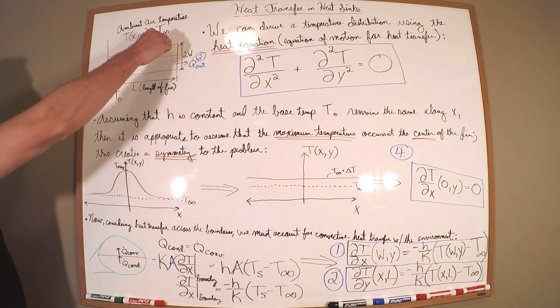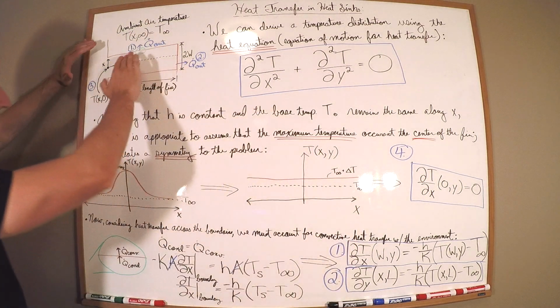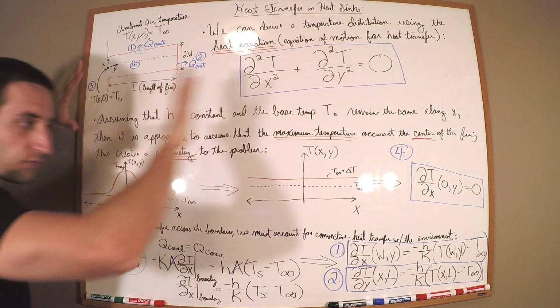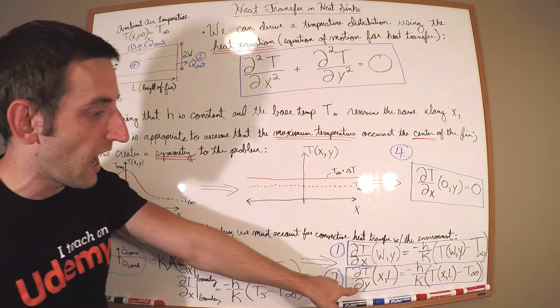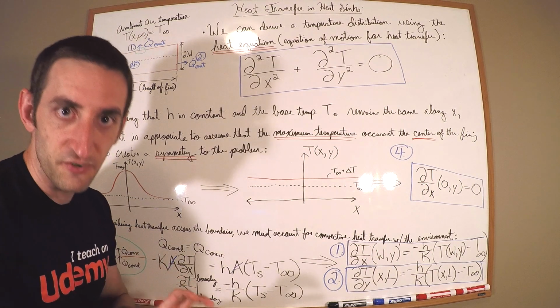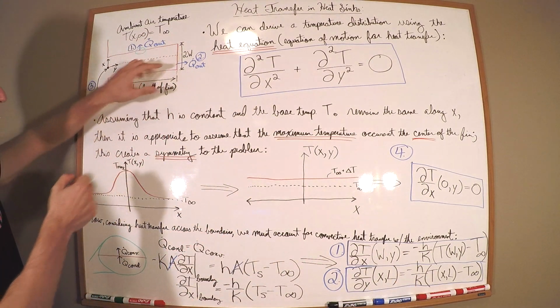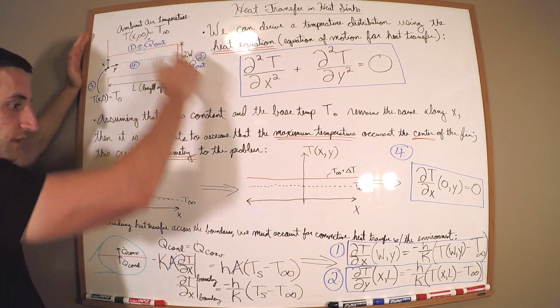Next one is going to be at the tip of that fin. All right? So what we need is the heat transfer to flow through in the y direction, flow through this surface as such. So this guy becomes dT/dy, because it's flowing in the y direction. The direction of the temperature differential drives that heat transfer. It's going to occur at y equals L along that boundary.